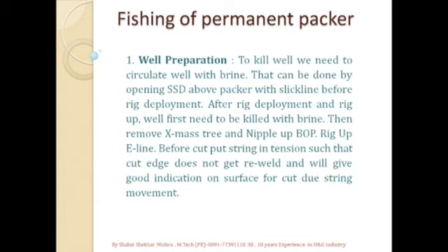Once the tubing has been punctured, or we have established communication with the annulus above the packer, then we deploy the rig. After rig up, we kill the well with brine, with circulation. Then we install a barrier and remove the tree.